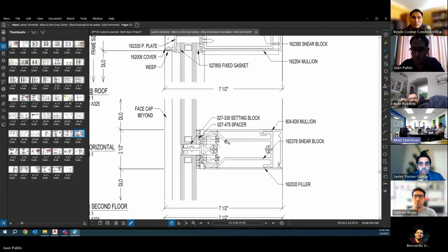Stay away from splicing an SSG vertical with an expansion joint because again, your glass will be adhered above and below the splice, so there's not any way to accommodate that. What about a hard splice? Hard splice is fine. Okay. It's just when we have the movement.